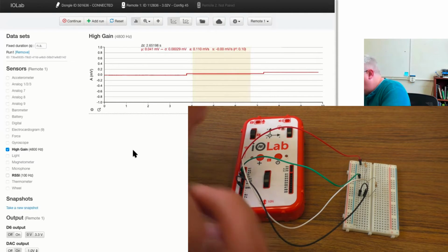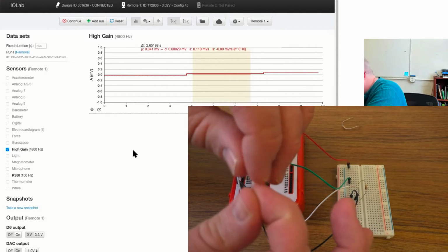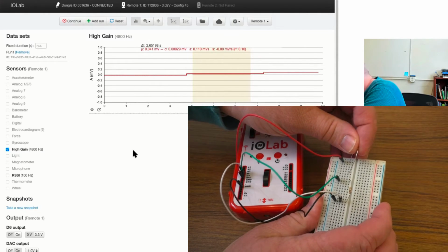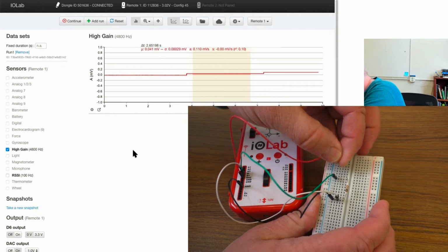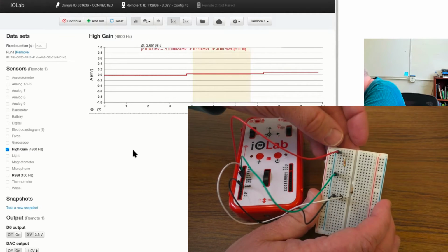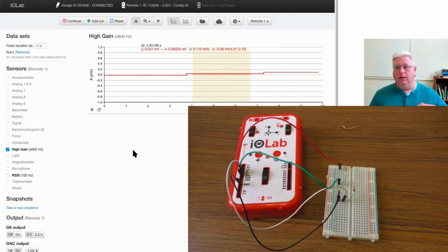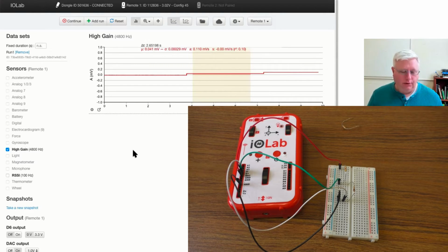And so I'll just take out that 10,000 ohm resistor and I'll plug in the 4.7 thousand ohm resistor right in the same spot. Okay, and then we can repeat what we just did, where we increase the voltage at 0.5 volt intervals, and see what happens to the current in this situation.